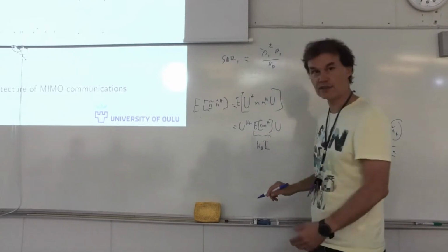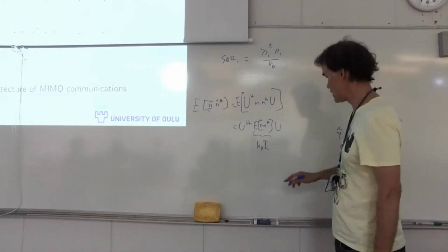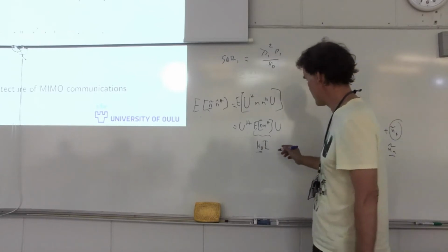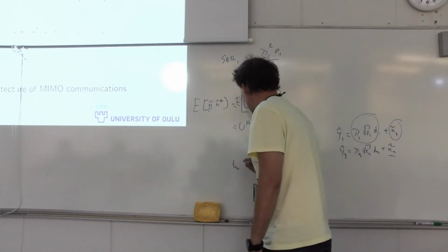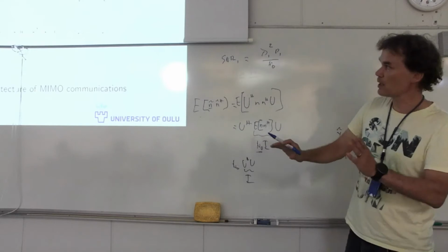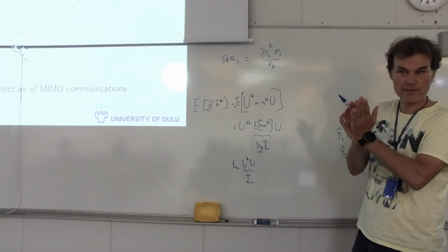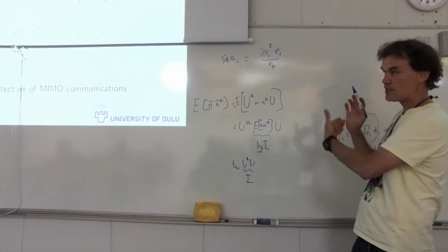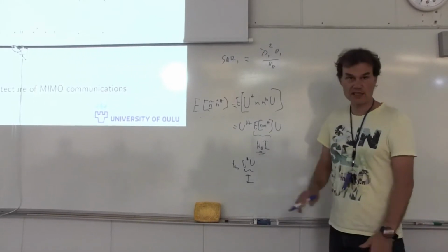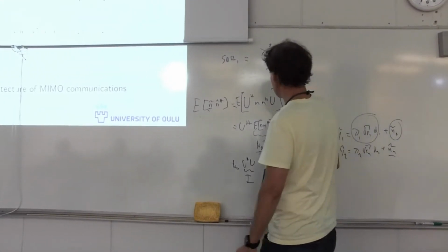And we know that the covariance of n is the independent noise added at the receive antennas, and has this structure, right? So it's independent. Both of these, both the noise processes at both receive antennas follow the same process, the same variance. Okay. So this goes in front. We have N0 U Hermitian U, and we know that this is the identity matrix. So multiplying the received signal by the unitary matrix U Hermitian does not alter the statistics of the noise. Okay. That's why we just have the same noise variance here, right?